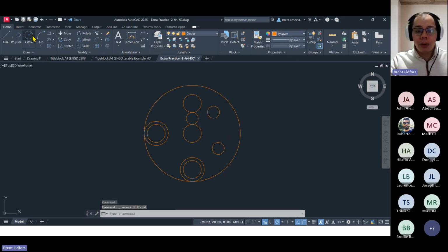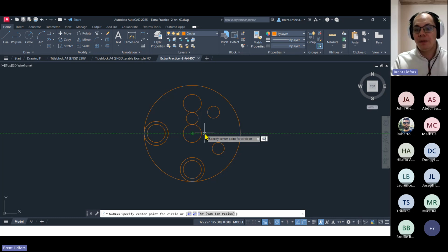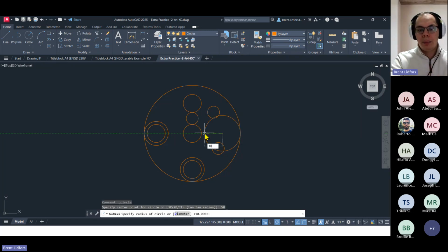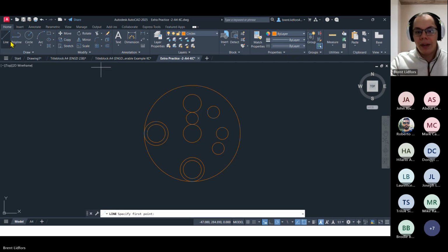Whereas if I use the tracking line and then go across and type in 50, AutoCAD's not going to assume decimals because I didn't type in decimals. So when I type in 50 and hit enter, put in my radius here, and then again, go to check that distance, it's precisely 50 units. Same if you did any angles. The angles you'd have to do a bit different.